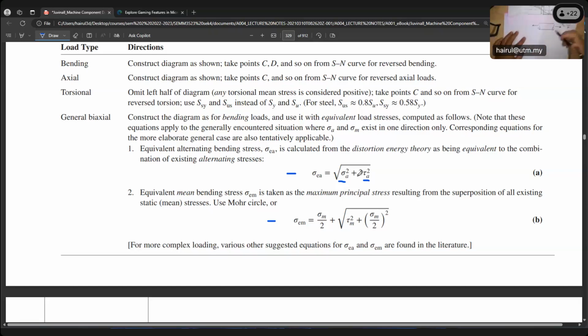But if you have a notch, or you have a shoulder. If it is plain, with just no notch, just a plain diameter, the distribution of your stress is just a straight line like that. Normal axial stress. But if you have a groove on your shaft, or a shoulder like just now, that's why I showed you the groove, you only have direct axial stress, so your sigma axial is F over area.